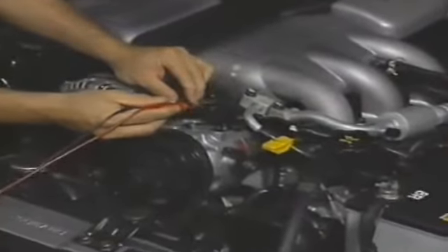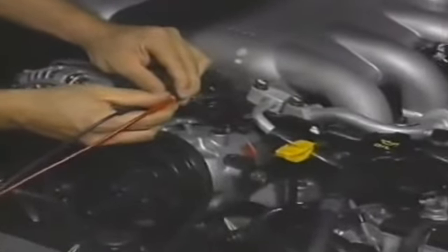If the compressor solenoid current was incorrect, check the solenoid resistance. If the solenoid resistance is not correct, the solenoid is at fault. If the resistance is correct, the ECU or the harness is at fault.